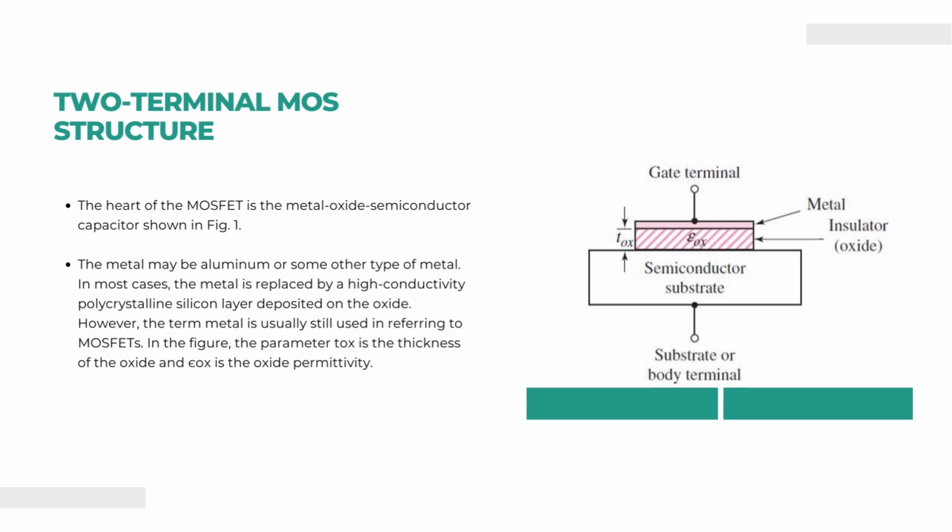The insulator is basically made of silicon dioxide. Now, in the research phases, there are various other oxides or other insulators which are also used, but in the basic structure a silicon dioxide layer is grown on the silicon surface. So, the three layers are metal, insulator and the semiconductor.